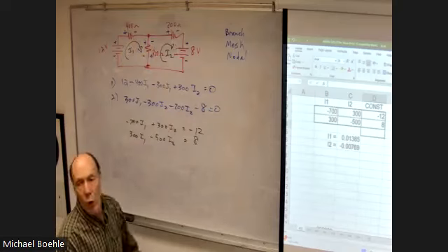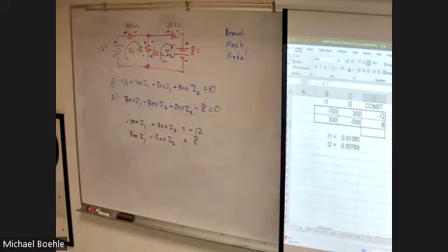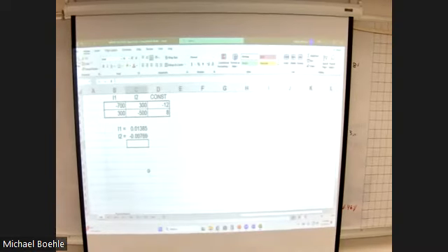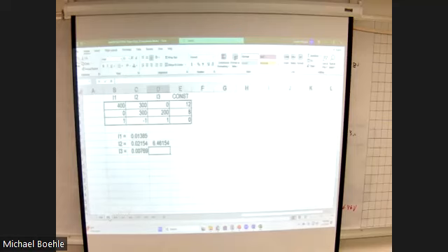Okay. And so in terms of using this to calculate it, you could also just do the difference between the two. If we look at the difference between the two, then the current in the 300 ohm resistor will simply be current 1 minus current 2, 21.54 milliamps, which when you go back to here is exactly what we had for our current 2.